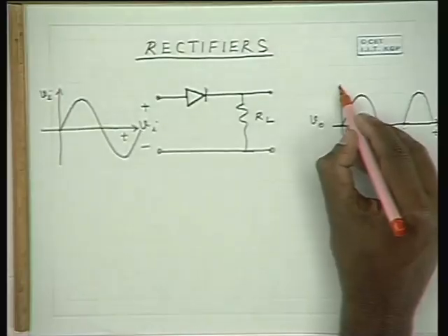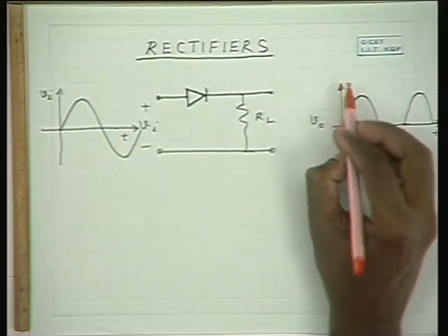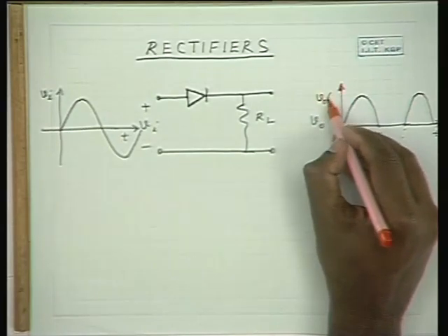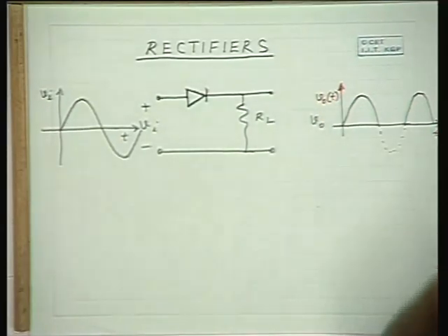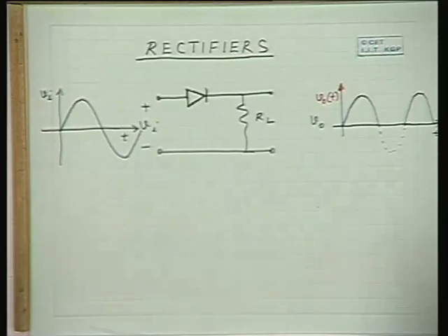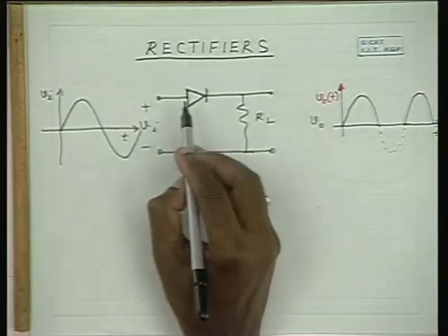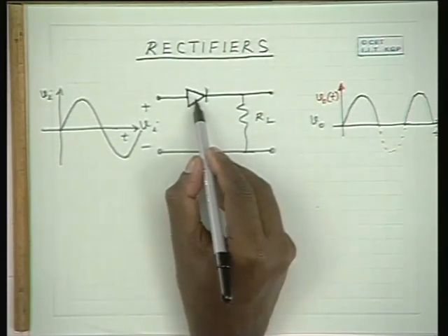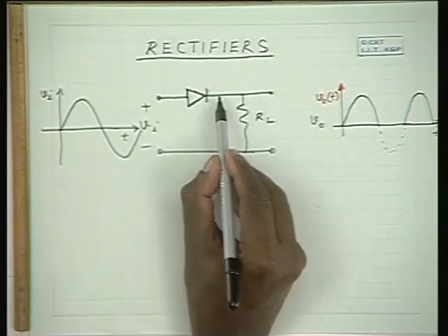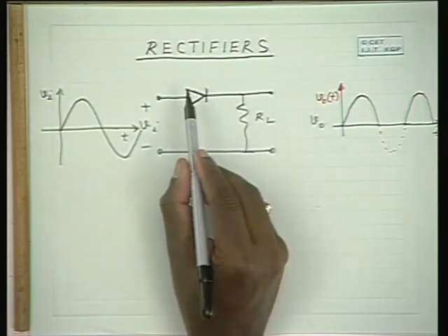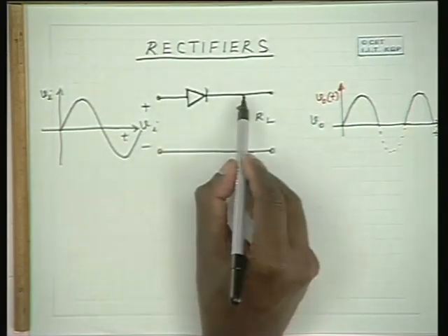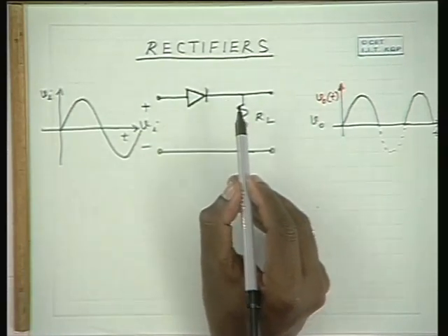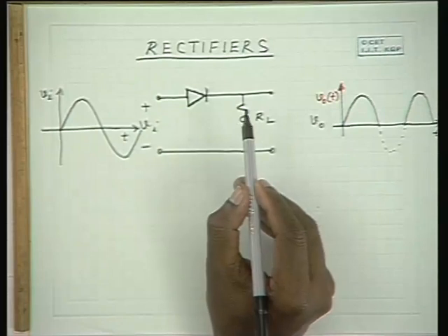How does it do this? So, this is the output voltage as a function of time. The diode acts like a short except for that small voltage V gamma drop and an additional voltage drop. At the most, how much voltage gets dropped across the diode for an appreciable amount of current? 0.6, 0.7, 0.8 at the most. Okay.